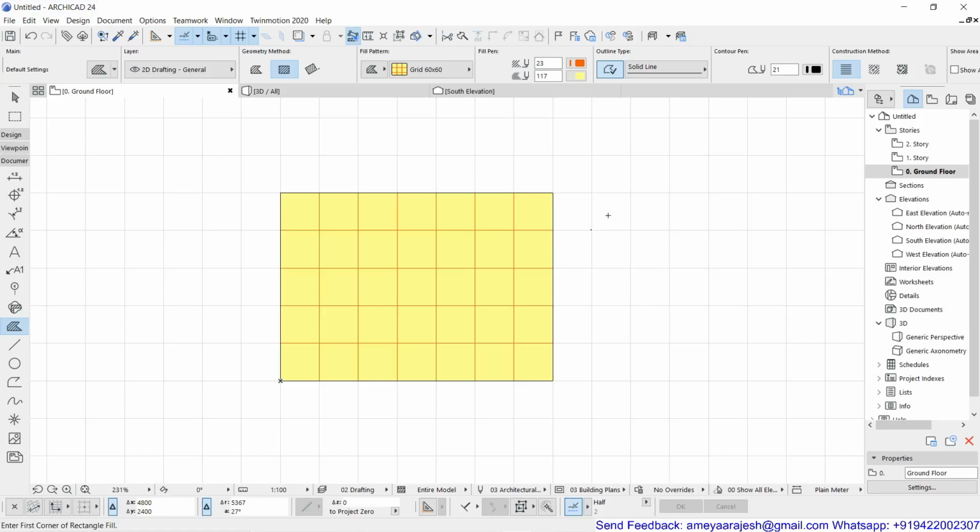If you have completed this basic drafting of the field or hatch, I'm going to show you a little bit of its editing now. Prior to that, just make sure that you are not engaged with the snap on grid points. That is nothing but this particular button, Snap Grid Snap. If it is on, please switch it off by either clicking on this button or using Alt S as a shortcut key, or hotkey, I can say.